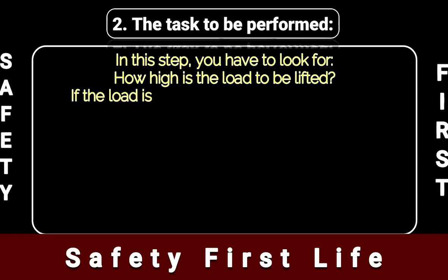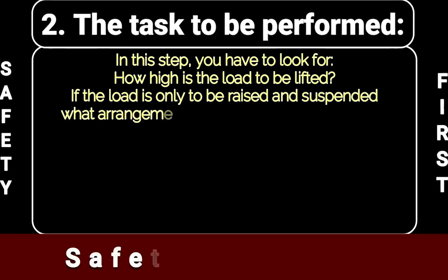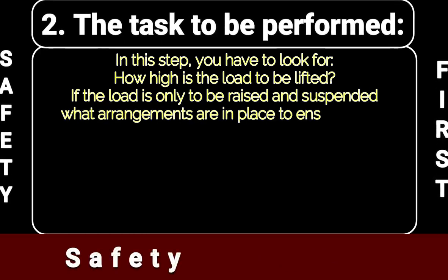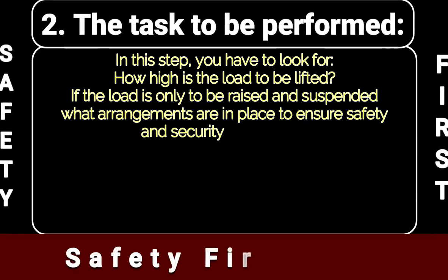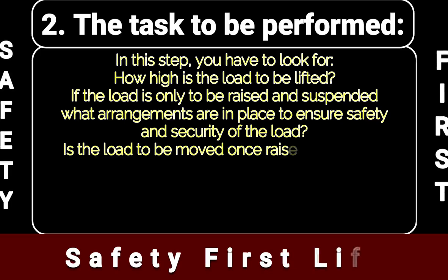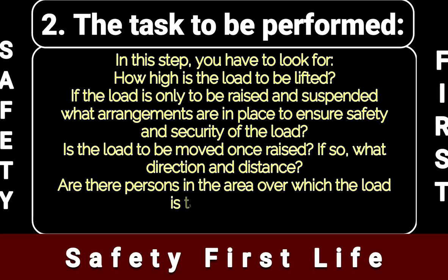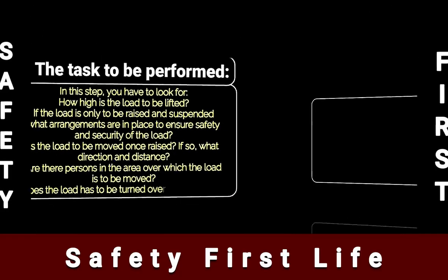If the load is only to be raised and suspended, what arrangements are in place to ensure safety and security of the load? Is the load to be moved once raised? If so, what direction and the exact distance? Are there persons in the area over which the load is to be moved? Does the load have to be turned over or orientated?